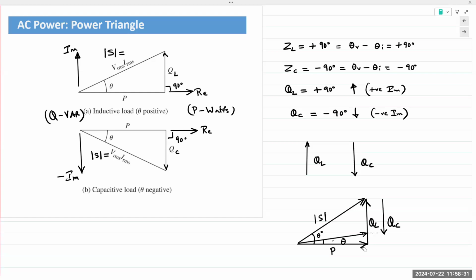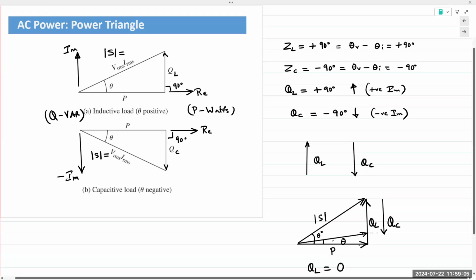You had the inductor that required a certain amount of power, right? So your utility company or your source is supplying P plus QL, but now you place a capacitor in front, it charges fully, and then from the second half cycle, or at least from steady state onwards, a huge portion of QL is supplied from the capacitor, meaning QC. Make sense? In ideal conditions, you would want QL equals QC, which is never possible.